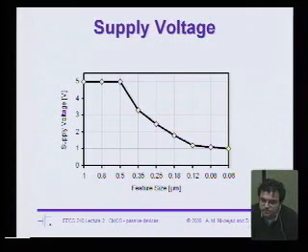Yes, Christian. You need the headroom to do cascoding and things you were talking about before. Sure, you need headroom, but why do you need headroom? The more devices you start stacking up in a cascode, the less headroom you have and the lower swing that you can have at the output. Okay, so swing. So why do we need swing? More fundamentally. Gain? Okay, well, no. How about? Your noise floor remains pretty close to constant, so if you lose your swing, you're cutting down your SNR. That's right. So it's signal-to-noise ratio.